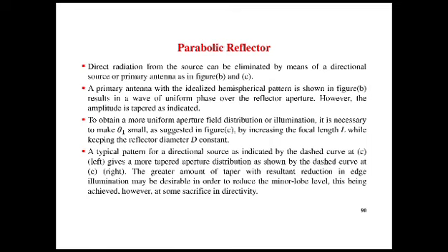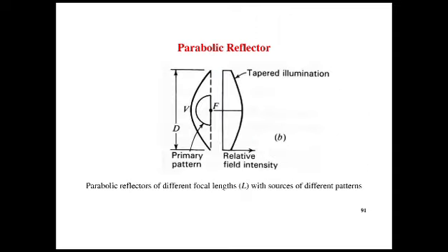The greater amount of taper will result in a reduction in edge illumination, which may be desirable in order to reduce the minor lobe level, this being achieved at the sacrifice of directivity.